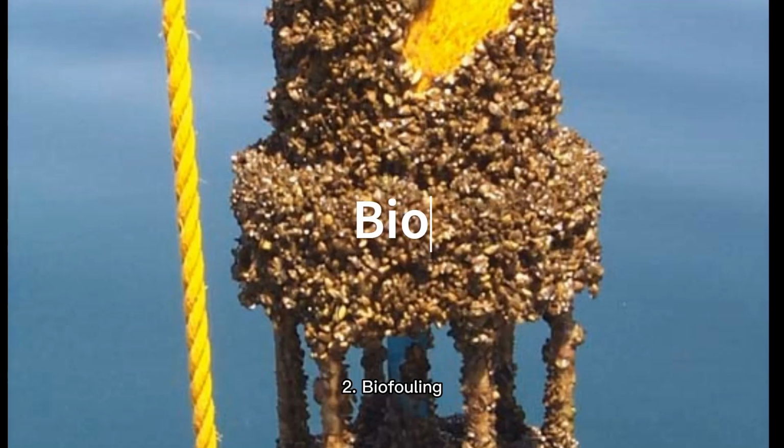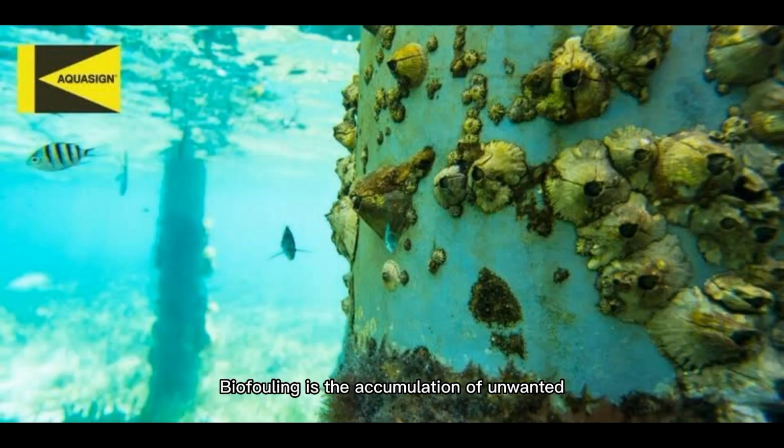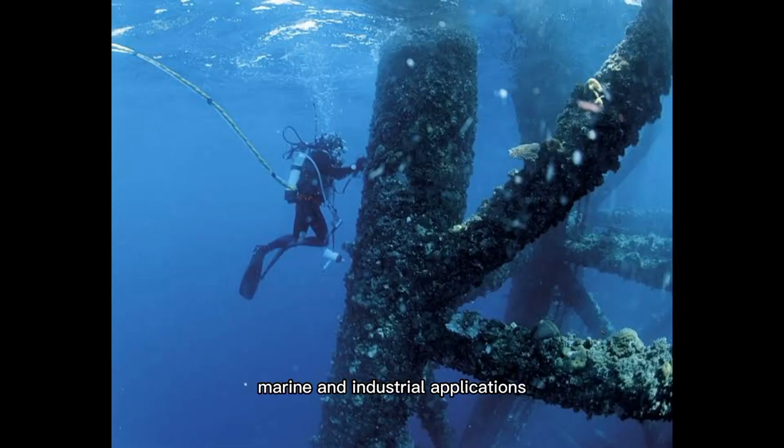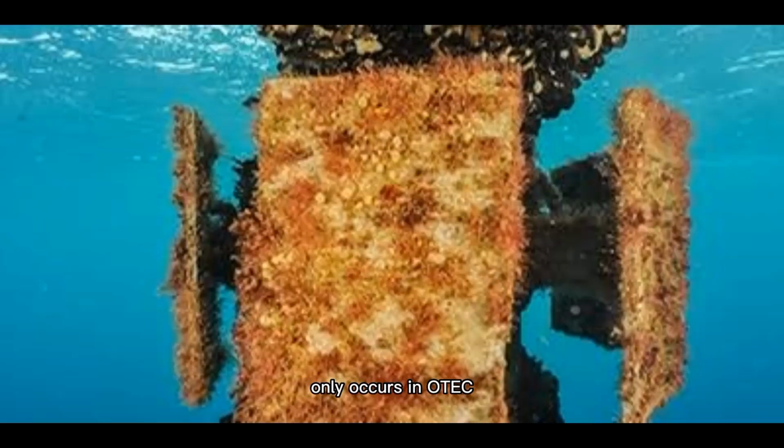2. Biofouling. Biofouling is the accumulation of unwanted biological material on surfaces, as found in medical, marine, and industrial applications. To have effective heat transfer, it is necessary to protect the heat exchangers from biofouling. It has been determined that biofouling only occurs in OTEC heat exchangers exposed to surface seawater.